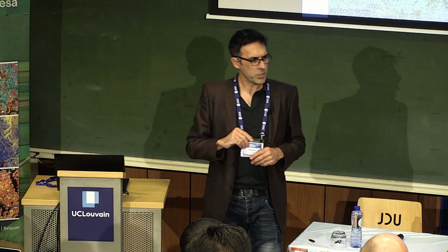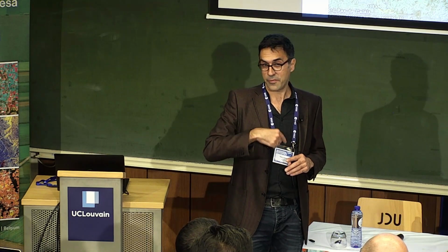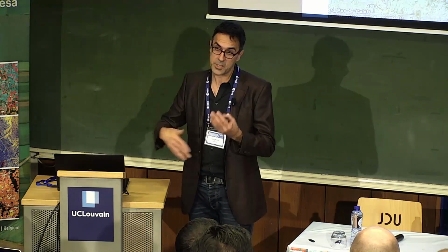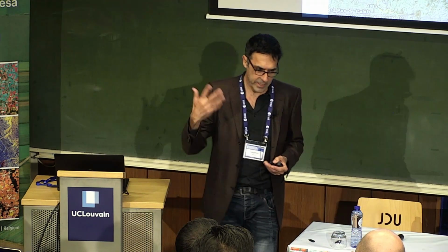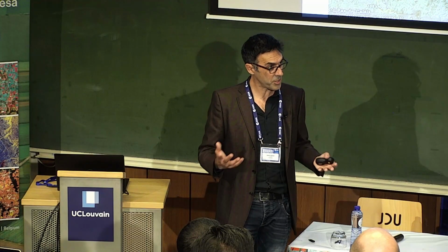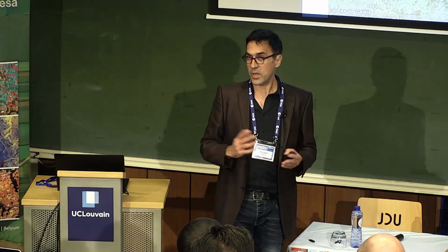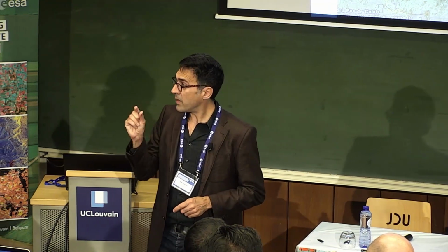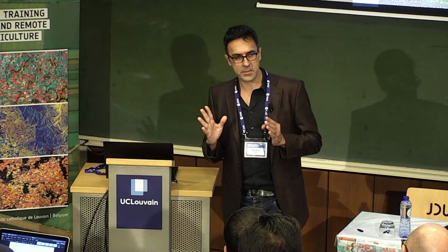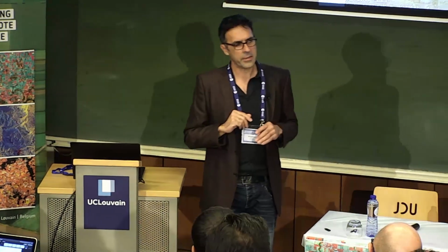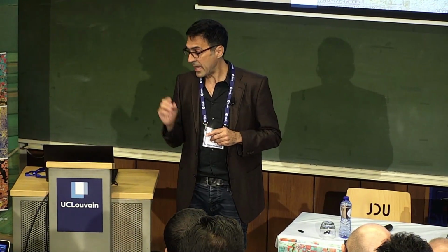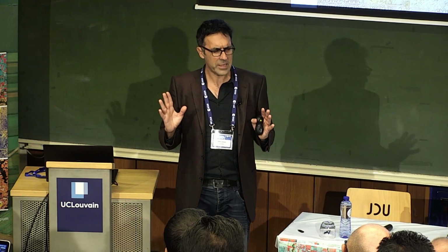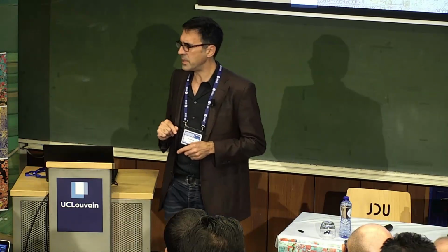around that number. So that means that we can transmit all these signals for 24 minutes, and then we have to charge the batteries. Solar panels have to get enough energy again to recharge the batteries to do it again. So a radar cannot be switched on all the time. And the shorter the wavelength, the shorter this duty cycle is. I think, from the top of my head, TerraSAR-X, for example, as an X-band satellite, 3 centimeters, has a duty cycle of maybe 5 minutes, or somewhere between 5 and 10 minutes.